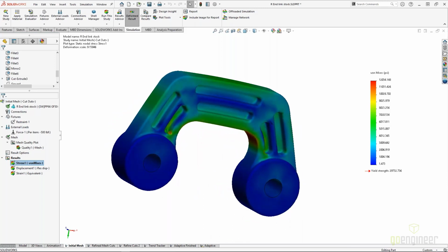But the question is, can we trust this, right? Because FEA is a numerical approximation, right? We're taking this continuous problem, we're breaking it up into elements. The finer the elements, the more the elements, the more accurate the solution, up to a point. You can have 1 million cells in this model and you probably will end up with the same result as 100,000 cells.